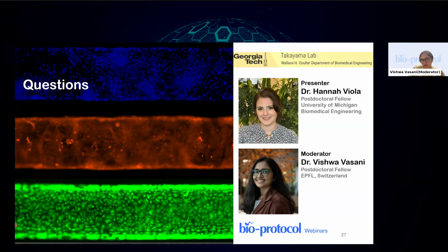Would you like me to read that aloud? Okay. For microfluidic channels that contain small radii on the longitudinal axis, do you utilize a bullnose and mill with a small step down, or do you select a specific tool that matches the solid model's radius feature? So I do the first one. I take a bullnose with a small step down.